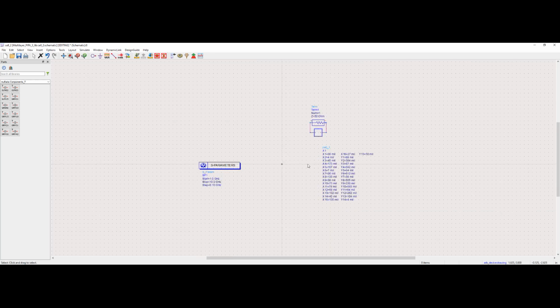The S parameter simulation controller frequency is defined next. Similar to the EM setup, we set the frequency range to be 0.5 GHz to 4 GHz. The frequency step we are setting is 100 kHz.